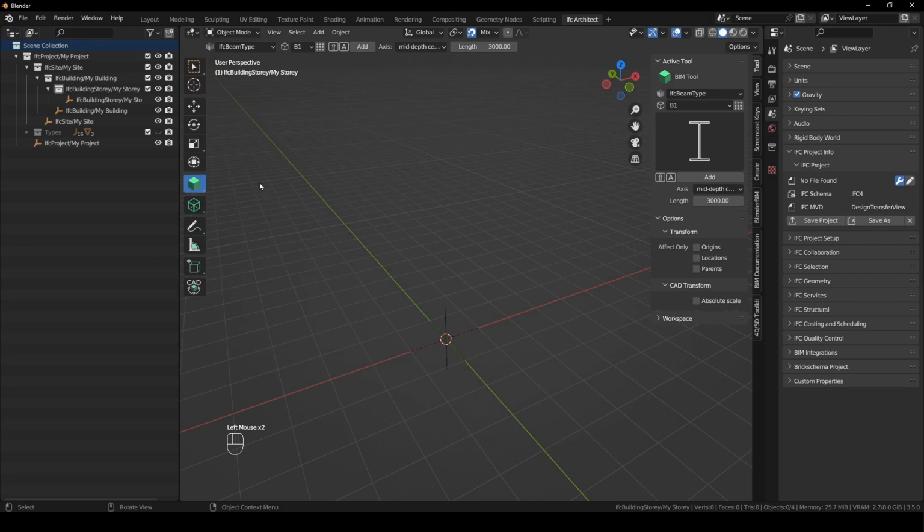And then just a quick hint, you can add this to a hotkey. So you can see that shortcut is quite long, Shift Spacebar Alt O. But you can add it to a hotkey by right-clicking and say add to quick favorites. So I've already got it added, so I'm just going to say remove. And then you can see add to quick favorites. So what that does is you can press Q, and then it will be listed here, basically.